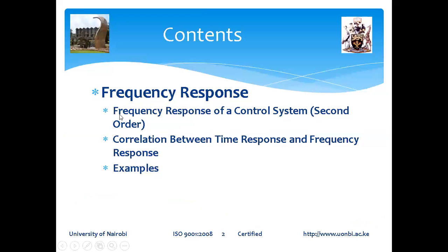So first we'll formulate the frequency response of a control system, and this will be a second order system. Remember when we were introduced to control systems, we said that we can just deal with second order systems, because a higher order system can be modeled or broken down into several second order systems.